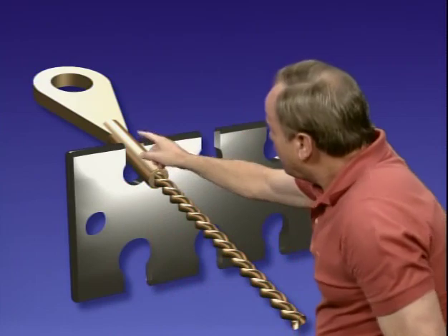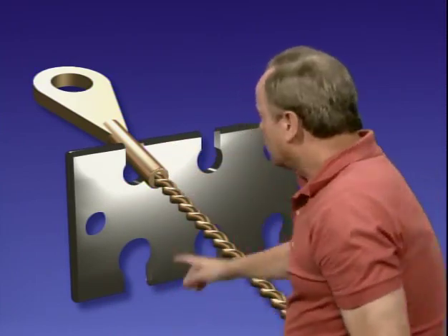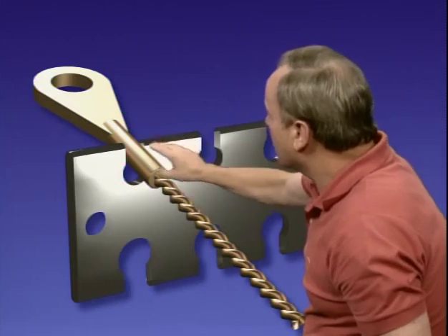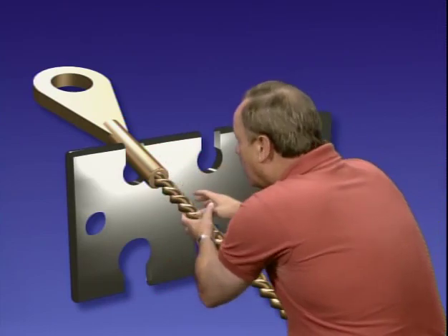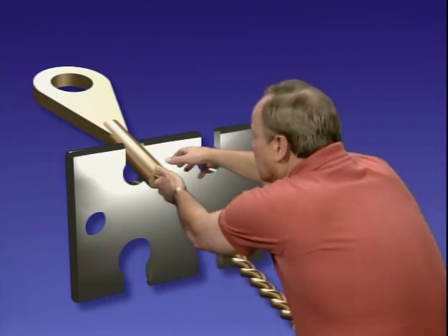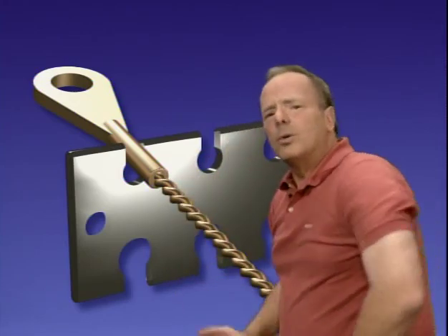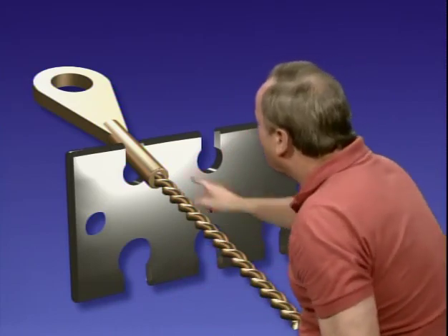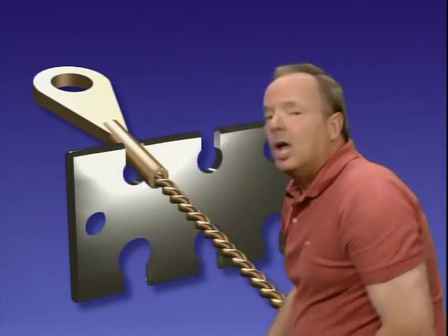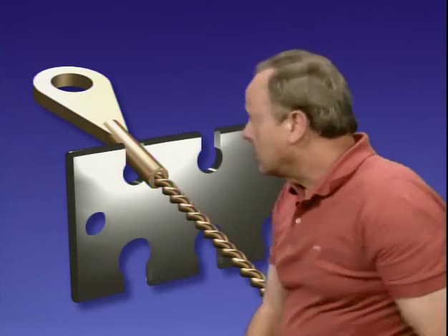Now, when you put this thing together, you want to make sure it lasts. Well, corrosion treatment, it's a good idea. It's not required, but that's one of the things you can do. But the real thing you're concerned about is it strong enough? Well, one of the things you can do is what is called pull or load testing to 60% of its breaking strength. And that's required, but that still doesn't show you that you met the manufacturer's requirements for swaging it on. Well, one way to determine that is just this.